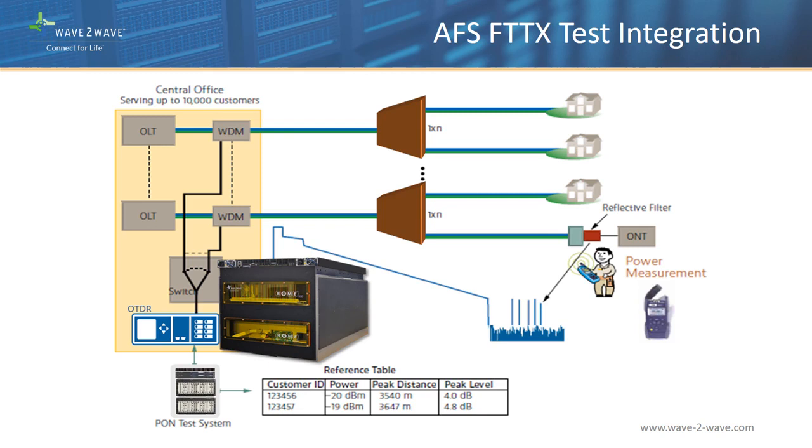The second last mile segment runs from the splitter to the ONT. Testing during installation and maintenance typically requires a fault location, connectivity check, and isolation. The highly capable instruments used to certify the feeder cable are not required for testing this segment, and so it is possible to use a less expensive and more user-friendly drop cable fault locator.